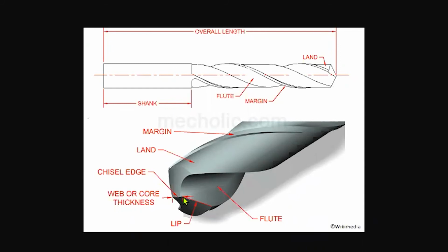The flutes that are machined into the drill bit allow for material removal through the length, but also make them able to flex. The longer the drill bits, the more they will flex. The more flex they have, the more likely they are to wander.